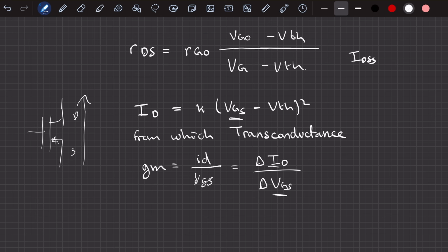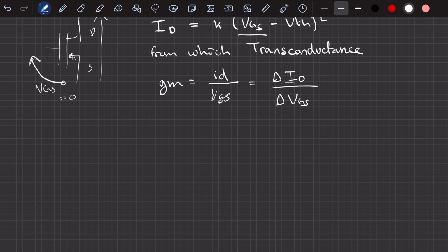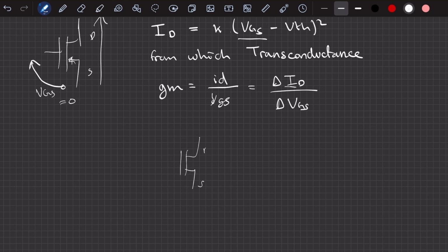So basically the maximum current through the device when the gate source voltage, which is this voltage over here, is equal to 0. VGS is the gate source voltage. So obviously you have your FET, you have source, drain, and you have a gate. And VGS is this voltage. This voltage controls how much the channel will conduct. So basically how much current you're letting through.